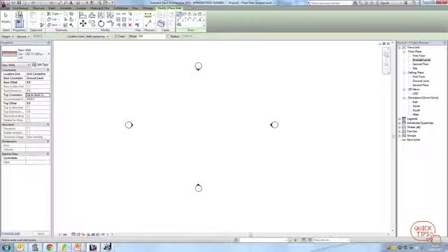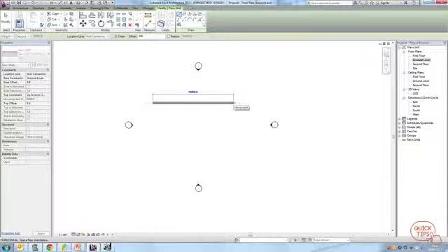we are going to create our walls. So if I just drag a wall here, I can make it 15,000 millimeters, or I can just type in 15,000 millimeters. So you can drag to how long you want it, or you can type it in by just pressing a number key on your keyboard, and it will bring up the editable box. So I want it 15,000 millimeters, and there you go.